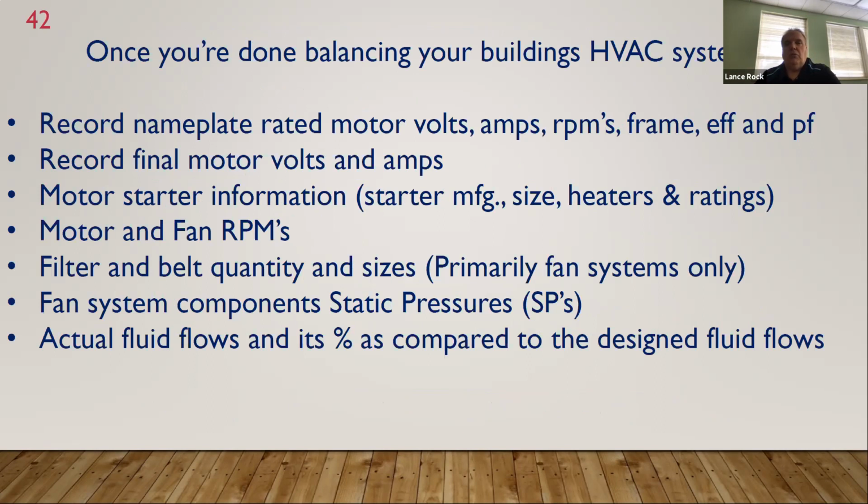Record nameplate rated motor amps, final motor amps, volts, motor starter information, motor and fan RPM, filter and belt quantity and sizes, fan system components and static pressures as a final, and actual airflows as compared to design. Next, please.